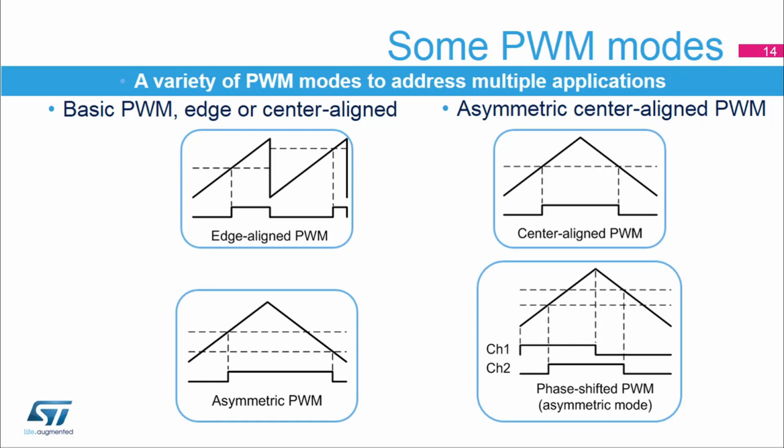This is a key feature for three-phase PWM generation for electric motor drives, since it allows you to double the frequency of the current ripple for a given switching frequency. For instance, a 10 kHz PWM will generate inaudible 20 kHz current ripple. This minimizes the switching losses due to the PWM frequency while guaranteeing silent PWM operation.